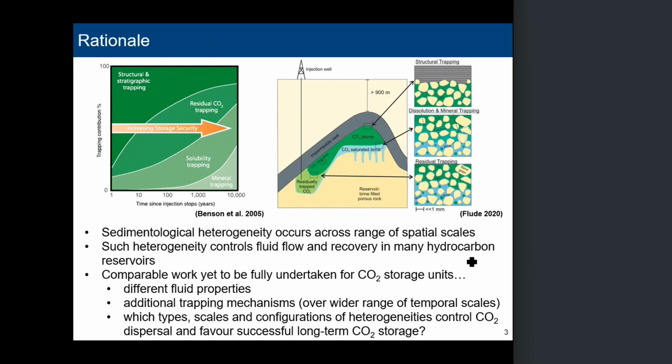Those are all aspects of trapping CO2 which are specific to carbon sequestration and that we haven't really thought about in the context of oil and gas. To illustrate those, we inject CO2 into a reservoir, and it moves under buoyancy towards the top of the structure. We're used to that style of trapping. As the plume moves up, some of that CO2 is trapped in the pore space by capillary trapping, referred to as residual trapping on this diagram.